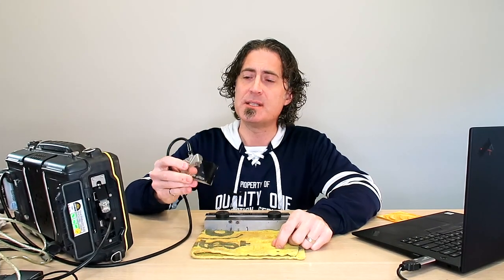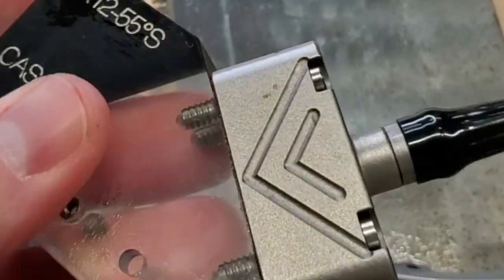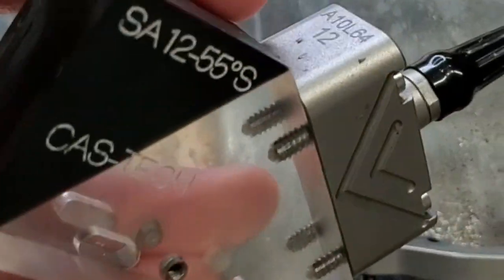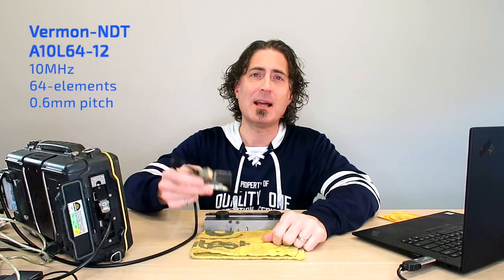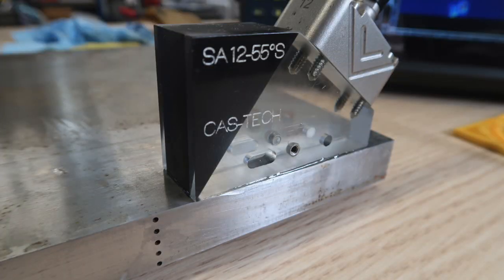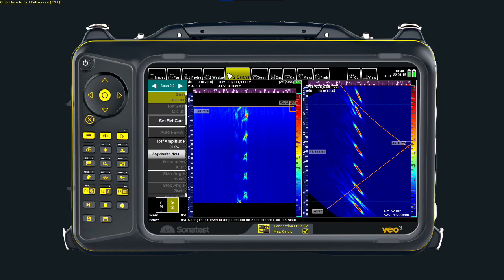We'll test it on some simple targets. First, I'll use this Vermon NDT 10 megahertz 64 element A12 transducer on this wedge, and we'll stand back a little bit from the targets just to pretend like we're on a real weld. Here I've got a stack of side drilled holes. On the left is TFMi and on the right is regular phased array. Those holes are really close to the surface, but at 10 megahertz, the resolution is really nice.